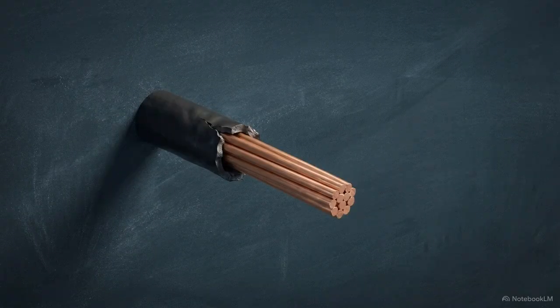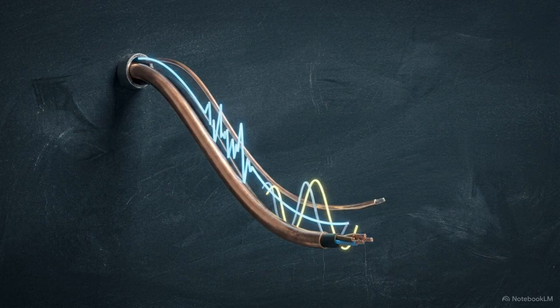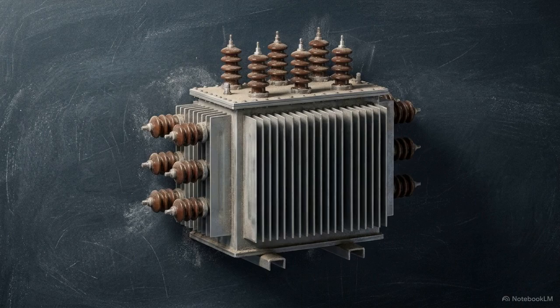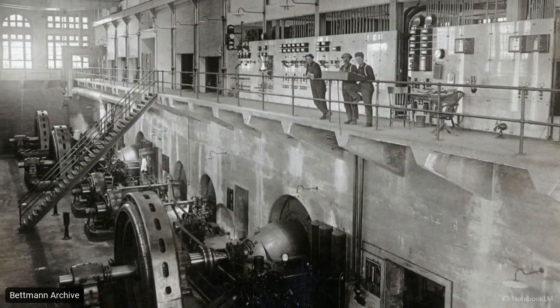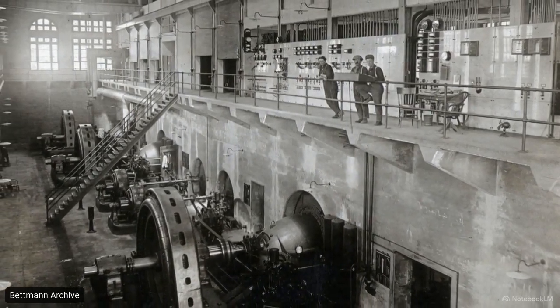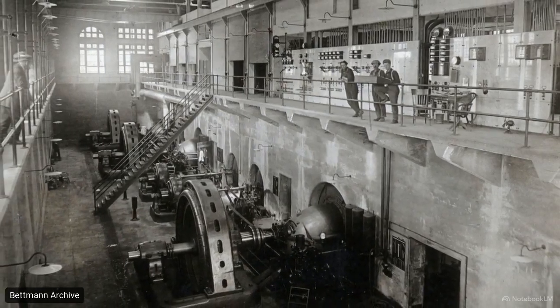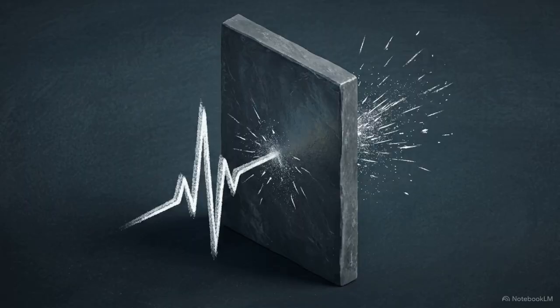This fast-moving energy will inevitably hit a terminal boundary, such as an open circuit, a physical switch, or a heavy transformer. The survival of the grid depends entirely on the rigorous wave mechanics that dictate what happens in the microsecond that impulse hits the physical boundary. When the traveling impulse strikes the boundary of the line, it cannot proceed. The energy is forced to reflect backward along the exact same path.